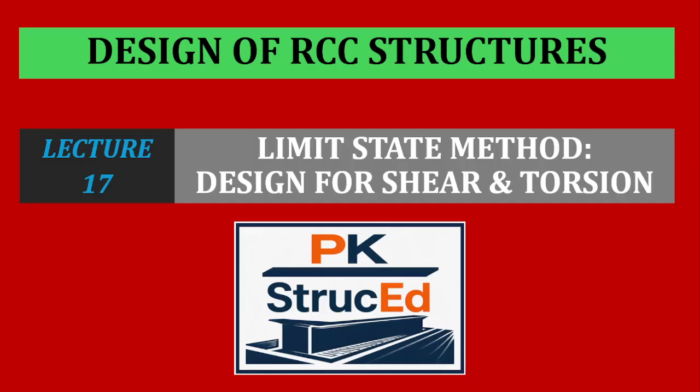So far in this course, we have mainly focused on the flexural design of RCC beams, where bending moment is the dominant action. However, in real RC structures, bending does not act alone. The beams are simultaneously subjected to shear forces, especially near the supports, as well as torsional moments, particularly in edge beams, corner beams, and beams which are supporting cantilever slabs.